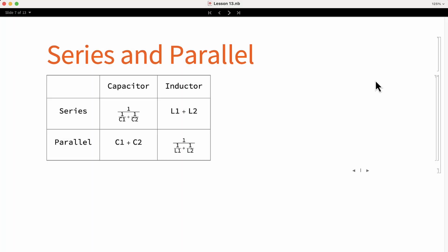If you remember, the equations for the inductors look very similar to the capacitor equations, but with the symbols V and I swapped. If we follow the same analysis using the inductor model, we reach the following formulas. Connecting two inductors in series results in a larger inductor, which is the sum of the two individual inductors, while connecting them in parallel results in a smaller inductor. In the case of capacitors, connecting two in parallel makes a larger capacitor.